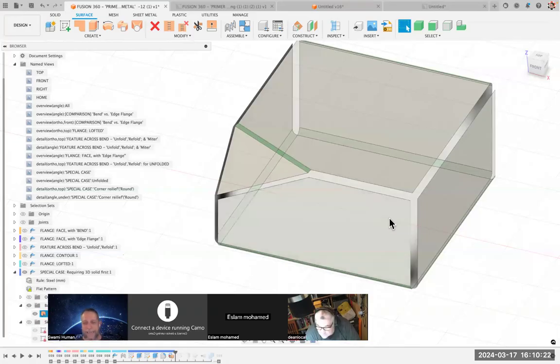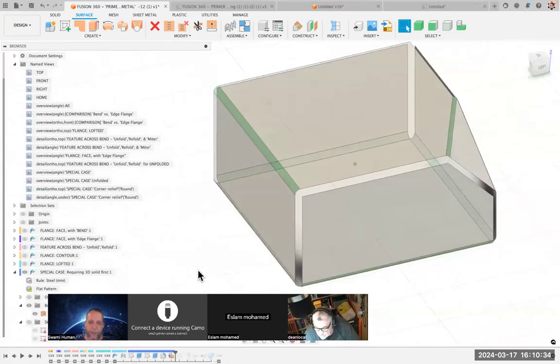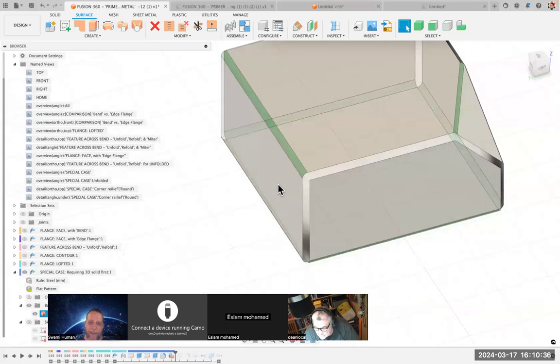Now we ultimately need to thicken this, right? Because it needs to be the thickness of our sheet metal, ultimately. But we need to make a stand-in sheet metal component that we're going to join it to. So I'm going to use this back face and come out here to the left outward and make a sheet metal face flange here. So go ahead and do that in the next step.